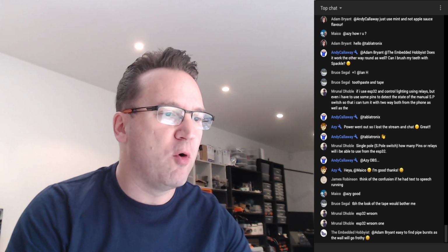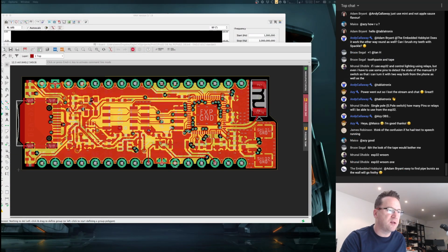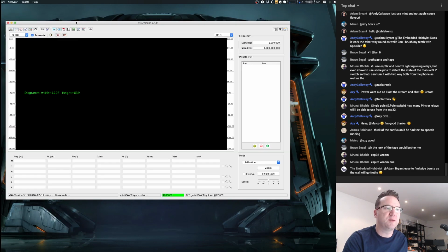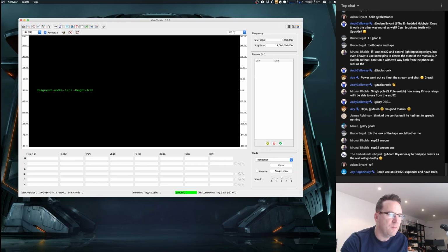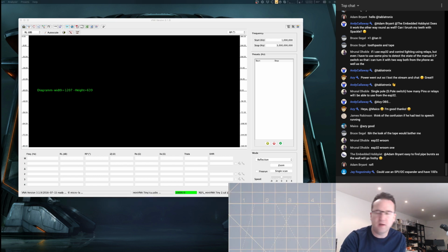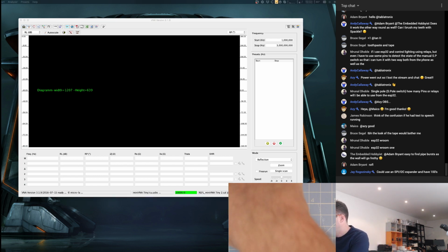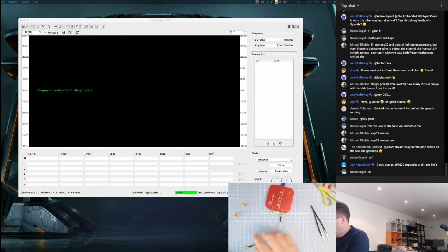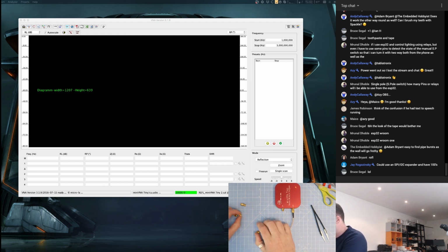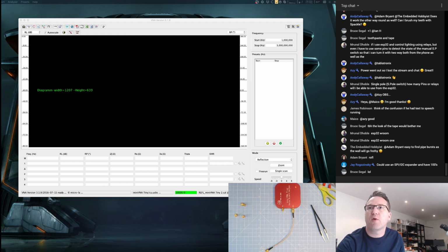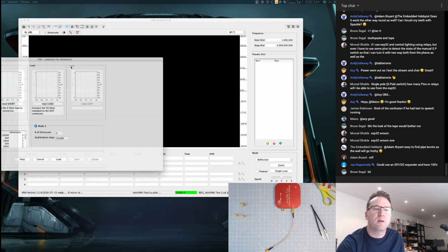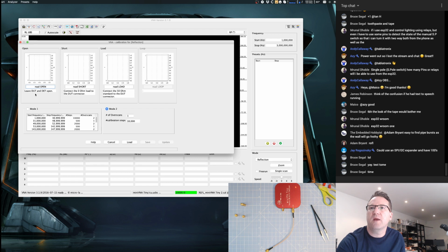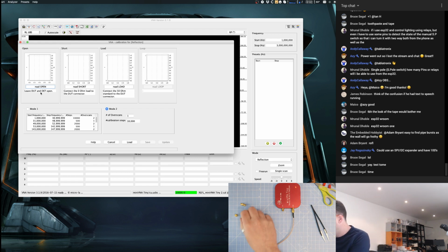So anyway, they're the two different boards I'm going to test today. So VNA time. We'll do some calibrating, shall we? Let me turn the cam link back on so you can see what I'm doing. Okay, so I need to do 3 steps of calibration. If I go calibrate, click on the calibrate button. Here it is. And so I need to do the open first.